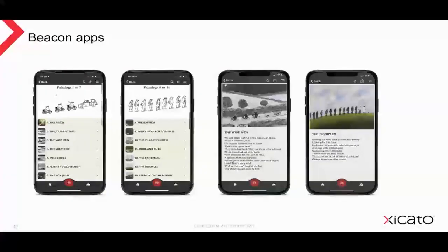In this particular case, an app has been designed which detects iBeacons. It will scan in the background for a particular value, known as a Universal Unique Identifier, or UUID, and then take action when it detects any beacon using that specific UUID. In the case of the Bert app, all the Bluetooth modules use the same UUID, and groups of between 6 and 8 nodes issue the same instruction. When the app detects a beacon, it registers the instruction and then automatically jumps to a page in the app that lists the corresponding group of paintings.